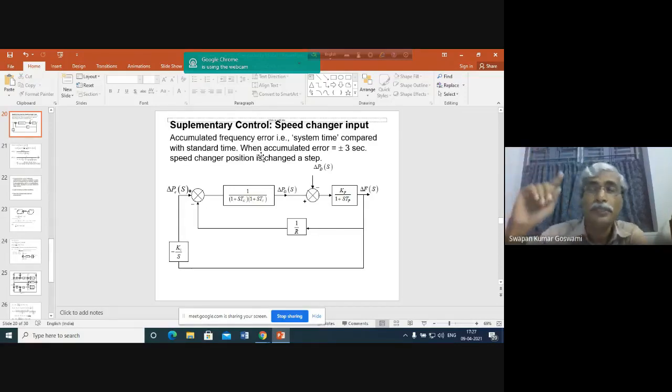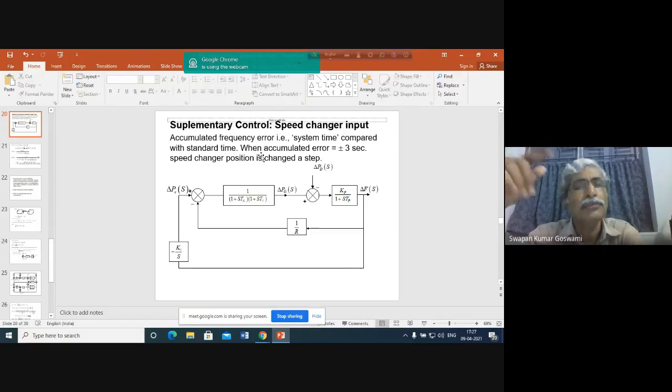But if you inject power during that time, again you will not be getting any price. So under above-normal frequency, if you inject power, you will not be getting any price. If you draw power, you have to pay no price. Below normal frequency, if you inject power, you will be getting higher revenue. Below normal frequency, if you draw power, you have to pay a penalizing amount of revenue.